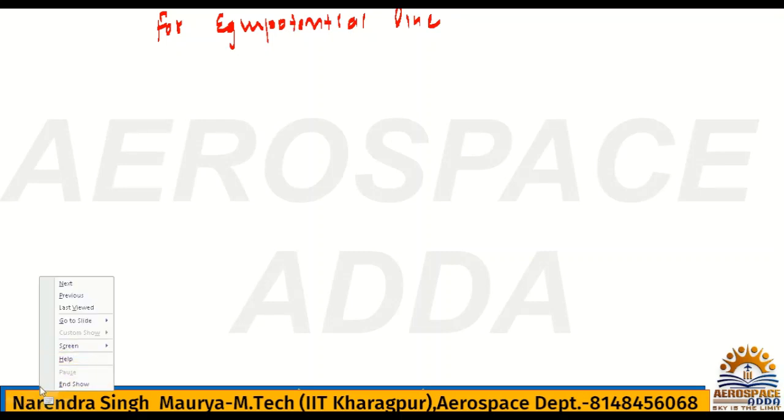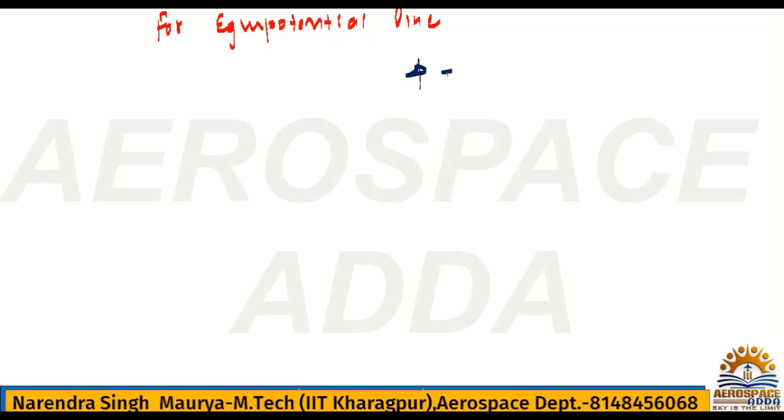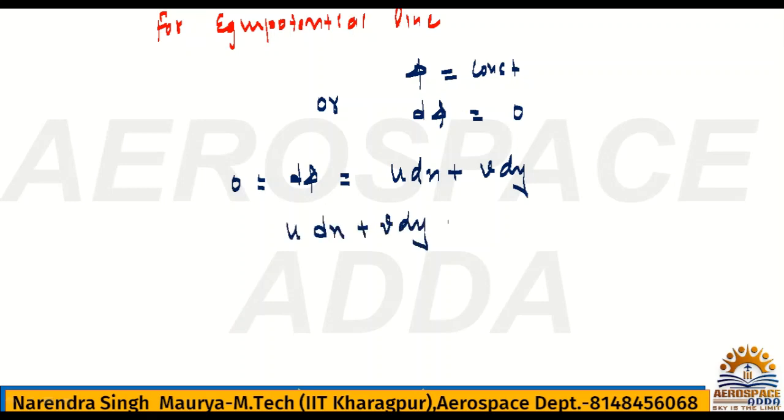Then what will be d phi? It will be 0. Yes or no? What result did you get here? You got d phi is equal to u dx plus v dy, and for the equipotential line d phi is 0. It means u dx plus v dy is 0.